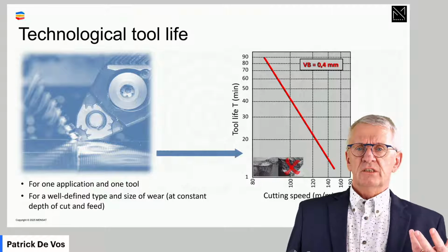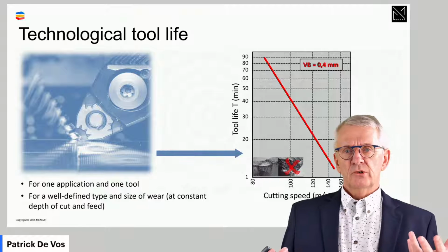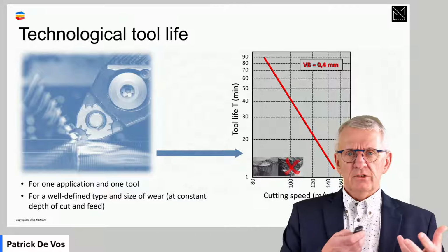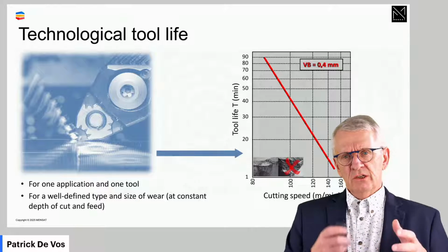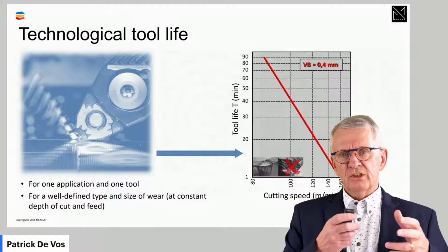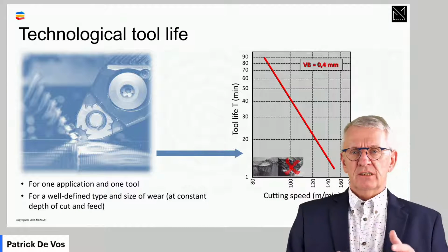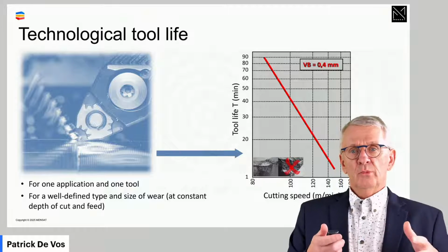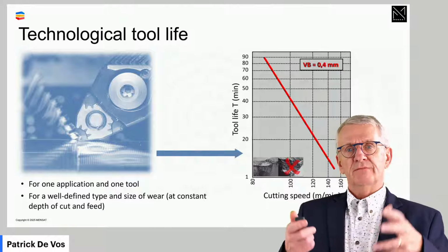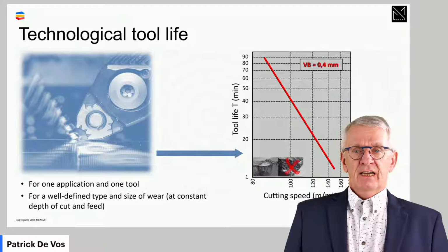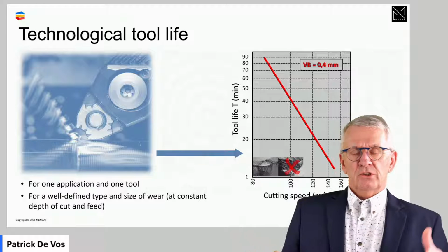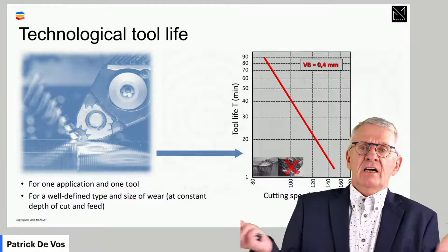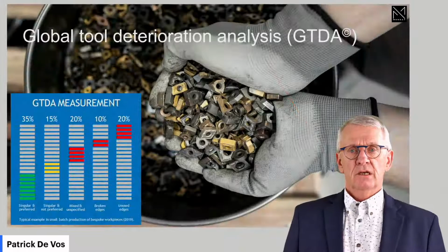In mass production, this is easy. If you have to produce 100,000 workpieces, you make tests for 100, 500, perhaps 1,000 workpieces. You find all the data and create the model, like you see here in an example. Then you know, in that application that you are going to run for the next months or years, how the tool behaves, and the instructions for the operators are very simple. Every 5th workpiece you index a cutting edge, and every 200 workpieces you index the insert if it's an insert tool, and so on and so forth. Life is easy. Life is beautiful in mass production.